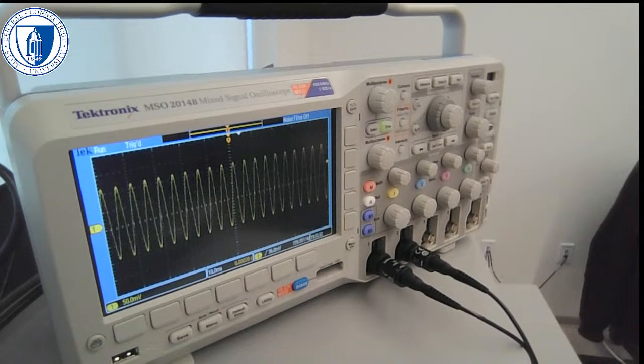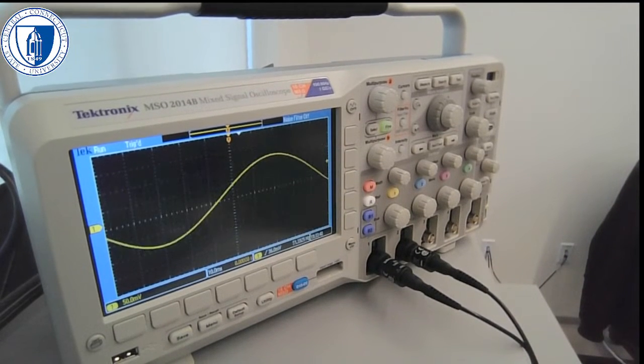So it gets faster, or I can change it to 10 Hertz maybe, and it gets much slower. We're going to use that signal generator to generate a sine wave to excite a circuit with a resistor and a capacitor, or a resistor and an inductor. Right? And you're going to have to set the frequency.